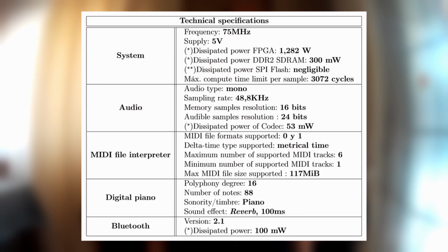To summarize, the final result has been the successful realization of a digital piano that can play MIDI files and uses wavetable synthesis, designed as a complete hardware system. Furthermore, this design is also highly parameterizable, allowing to easily configure both the maximum number of supported MIDI tracks and the polyphonic degree. For this presentation, a version has been implemented with the following specifications.